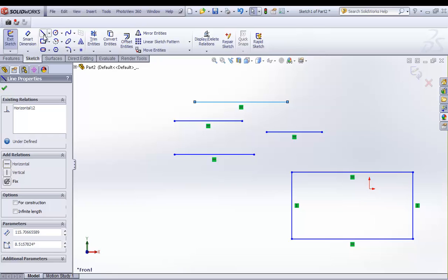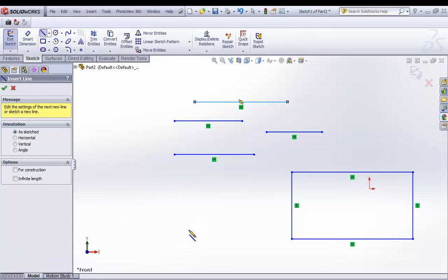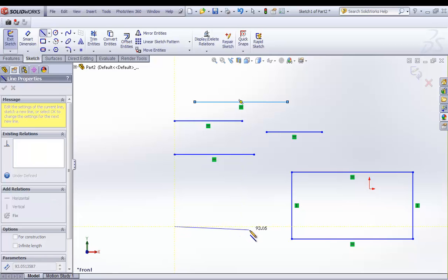Taking that a step further, if I were to go into the line tool again, you can see this dashed line. It's giving me some sort of feedback. So if I were to click now, I'll be vertically under that point, and my cursor shows that I'm vertically under that point there. If I were to click now, that is yet again confirmed by that yellow projector line. If I were to go along this yellow projector line, I'm not sure you can see this on your screen. You need to have really good contrast for that. I can see a yellow projector line, and it gives me some sort of easy approach to go 90 degrees to the home position. So I'm going to click now, and that's another way.